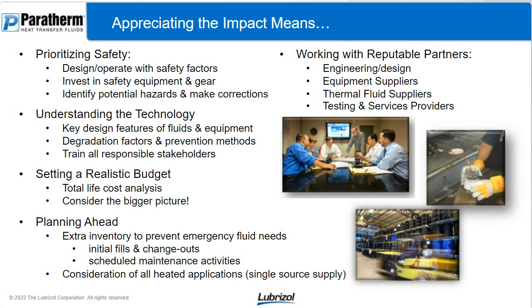Prioritize safety if you appreciate the impact. So design and operate with safety factors in mind. Don't spec a fluid that's up to the maximum operating temperature that you're going to be at and leave yourself no room for overshooting temperatures. Make sure that you have the safety equipment and gear, PPE, and the pressure release valves and the check valves and the proper signage and the proper leak protection or collection facilities.